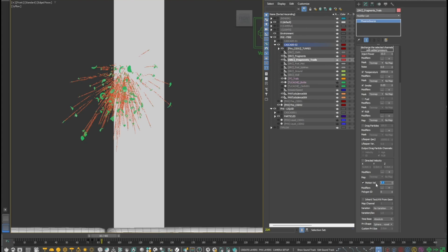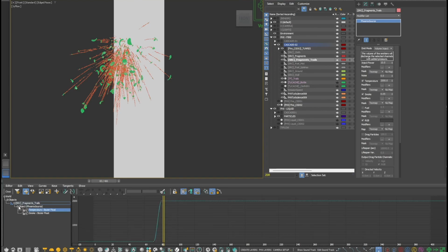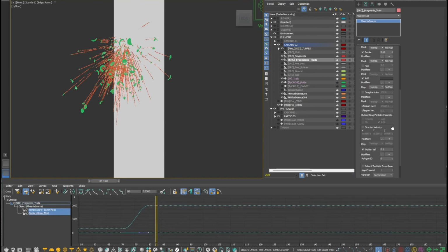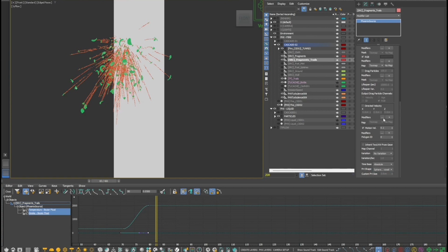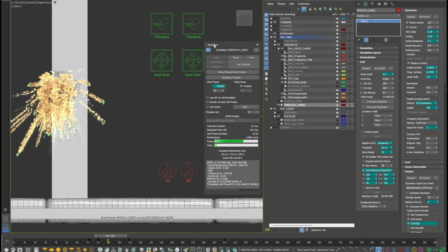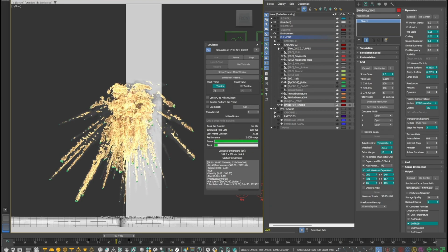The reduced velocity will help the fluid to stay behind as a trail and not try to move forward along with the particles. The temperature value and the smoke amount are animated again, and the timing is set to absolute. Both of these sources emit dark gray RGB colors. We'll talk about the colors later when we look at the shaders.